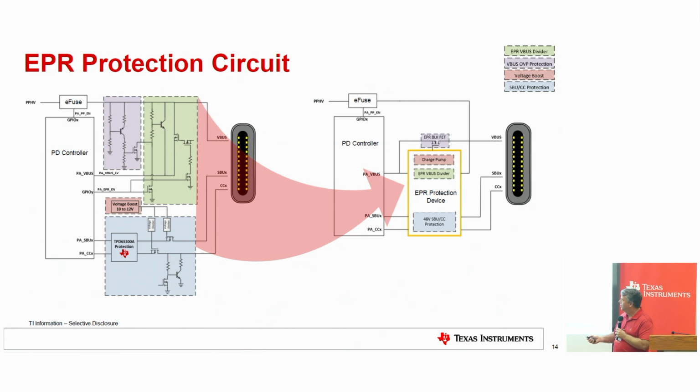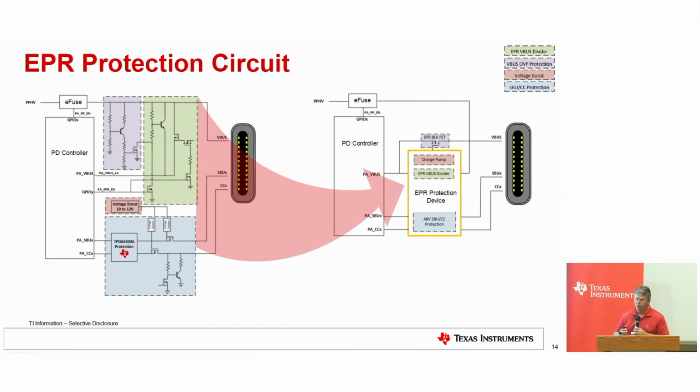The circuit in the purplish color here on the left is a comparator. What we do is guarantee that we're always running safe. Now that we're dealing with higher voltages and we know that the max voltage on our part is 20 volts, if something goes wrong, or at power up the power supply on one end is still ramping down, because sometimes they take quite a bit of time to ramp down, and let's say it started at 48 and it's sitting at 40 volts, we don't want to bring that into our part.